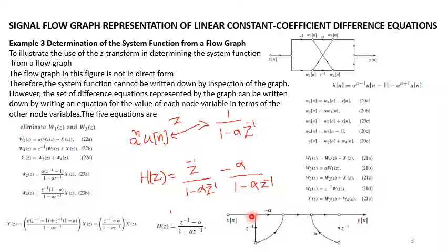So that's the direct form 1 implementation. You understand, direct form 1 implementation is the one in which you straight away write or draw the figure for the given expression without simplification. So it has zeros followed by the poles.